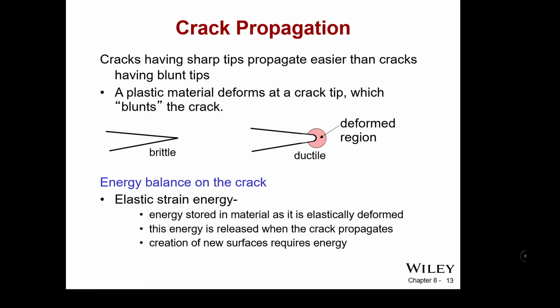This has to do with crack propagation, and that means that cracks tend to have a sharp tip in a brittle fracture rather than a blunt tip as in a ductile one. A brittle fracture is going to be a lot less plastic in its behavior, and therefore it's going to be much faster moving through the material. The brittle crack is going to move at a much faster rate typically, and that's another part of the reason why they fail explosively in experiments.